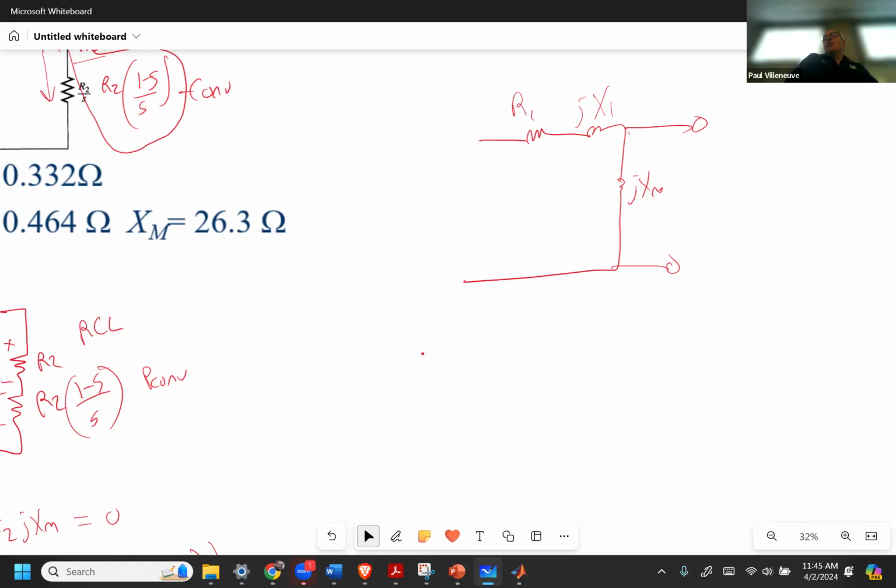Not sure? What are the rules about finding Thevenin equivalents? Turn off all other sources. How do you turn off all other sources? The voltage is the open circuit. Tracing by the internal equivalent impedance in an ideal voltage source, how much internal impedance does it have? 0, right? It's a short circuit.